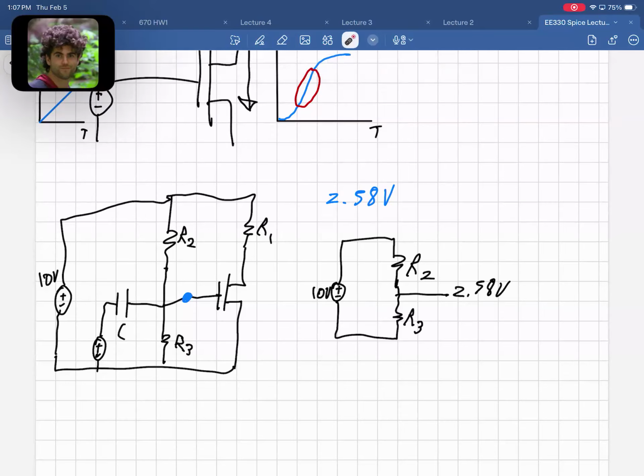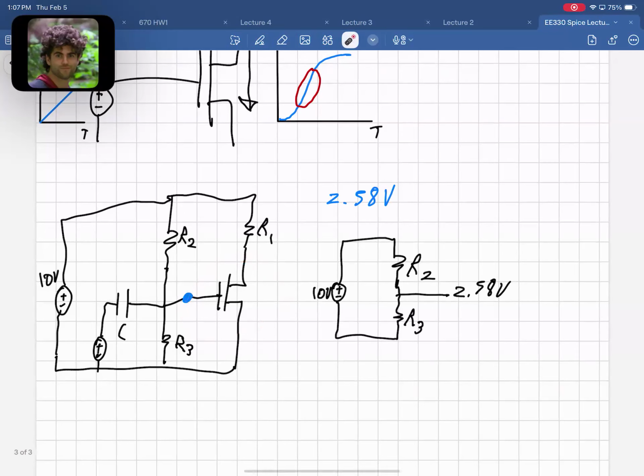And I can't believe I went so long without explaining this. But MOSFETs don't have any current that enters the gate. So you reference this voltage here, but you have no current that flows into it. So this approximation works fine just because you have the capacitor on the left side, and you essentially have another capacitor on the right side that doesn't flow. So there's no current here, and there's no current here at DC, and therefore we can say this is valid. Does that make sense?